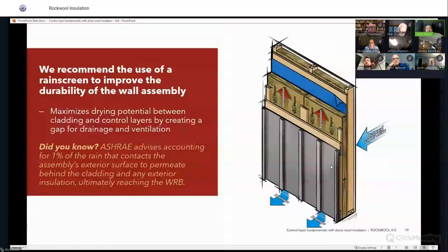But also, vapor molecules are lighter than air molecules. So having that ability, as it comes through and stays in the vapor form, to have an outlet up here at the top is going to give that vapor a release point, drying that system out and keeping it more effective. Another benefit of having the strapping on that assembly for the rain screen is you're going to provide a 3/4 inch channel, or however thick that channel is. And what's really nice about that is it's going to take the pressure off the siding from a paint aspect.